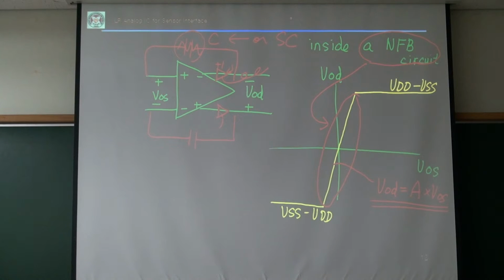Okay, a switched capacitor works like a resistor. The switched capacitor is fine, even with a high RO. Now, we don't want to add this unity gain buffer to drive resistance, because there is an alternative way, right? We can use just a switched capacitor without this unity gain buffer, right? So we usually don't use a unity gain buffer in a fully differential amplifier. Instead we use just a capacitor load instead of a resistor load. Okay.